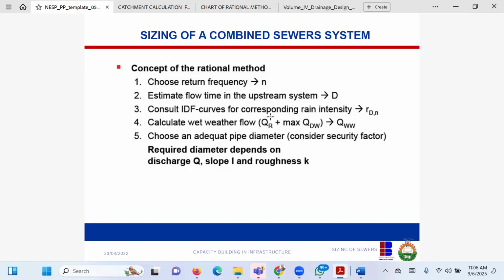You choose which appropriate rain intensity. Lokoja is about 120. Abuja is about 100 for a 1 year. When you start going for 5 years, you now start going maybe 120, 140. Most states in the south, the 1 year return period is about 100, 120. Except Lagos, that is about 100 too. Bayelsa is around 120. If you start going up north, like Sokoto, if I go back to that chart, Sokoto is around 70, 80, 90 for 1 year.